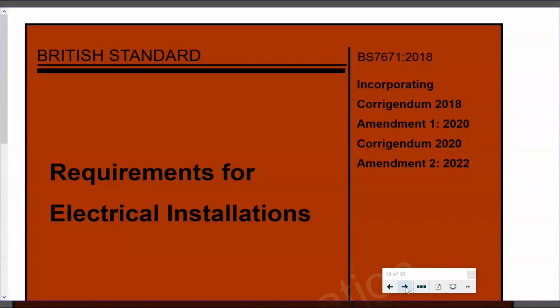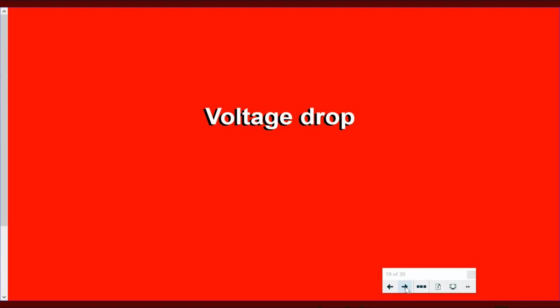Hi there, welcome to this second in the videos with regards to the initial steps for cable sizing. Previously we selected a 6mm squared cable for that 3 kilowatt load on the 20 metre run of twin and earth, 2-core and earth, PVC sheathed cable, so flat twin and earth. So now we're going to look at the voltage drop calculations for that installation.